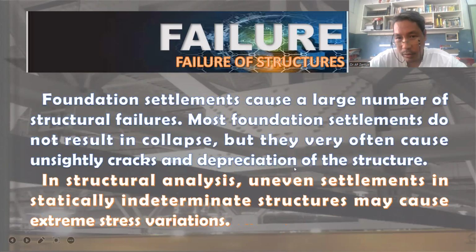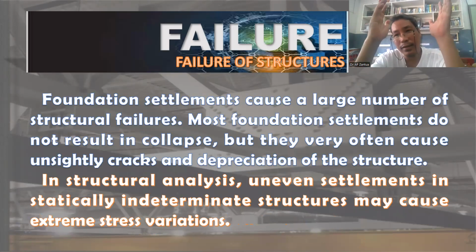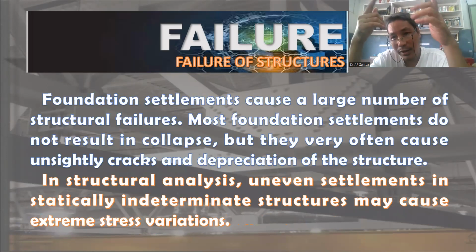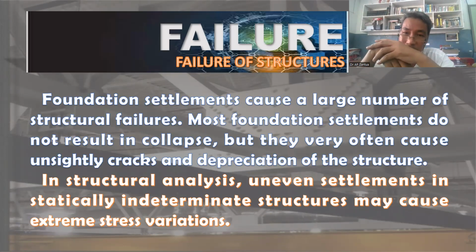Foundation settlements cause a large number of structural failures. Most foundation settlements do not result in collapse, but they very often cause unsightly cracks and depreciation of the structure. So even if that is not dangerous, the mere presence of cracks on the structure will wreak fear from the occupants.